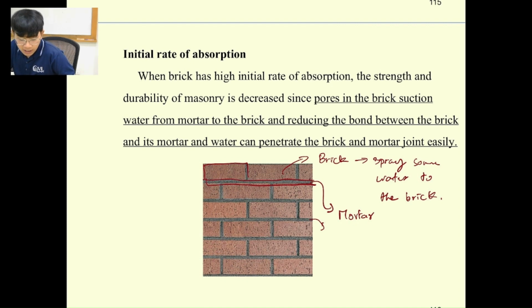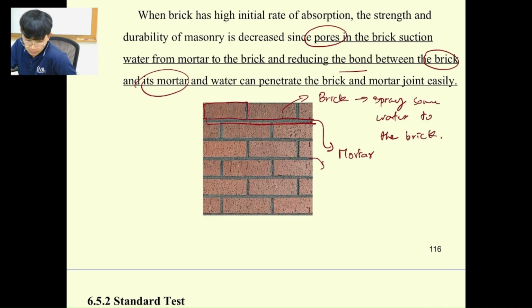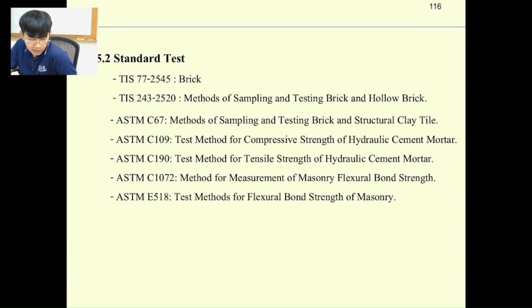So please be careful. The pores in the brick can suck the water out from the mortar, and it's going to reduce the bonding between the brick and the mortar. And these are the testing standards over here.